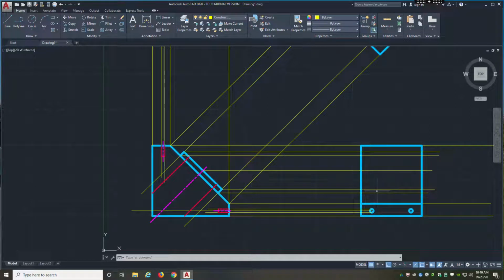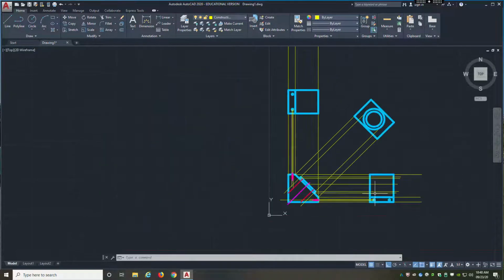There is another method called the miter line. So I'll be able to do the miter line. I guess I could do it here. What that does is it gets rid of the auxiliary view. Basically, it's a 45 angle line. You would draw technically a 45-degree angle line, so it's 135 degrees.